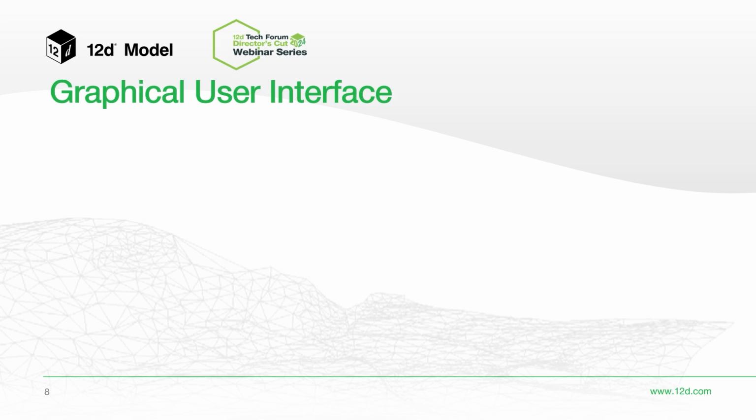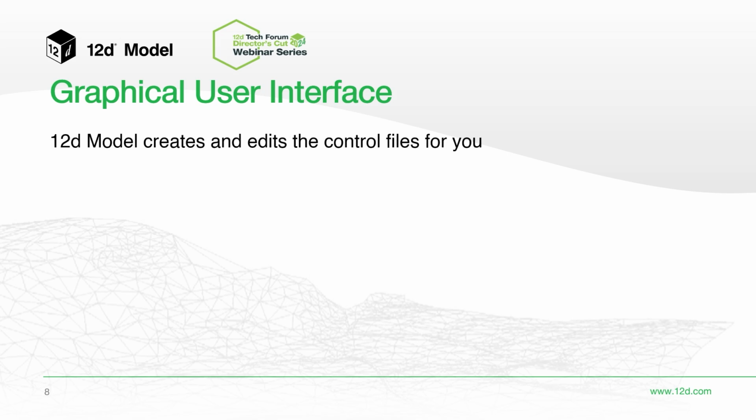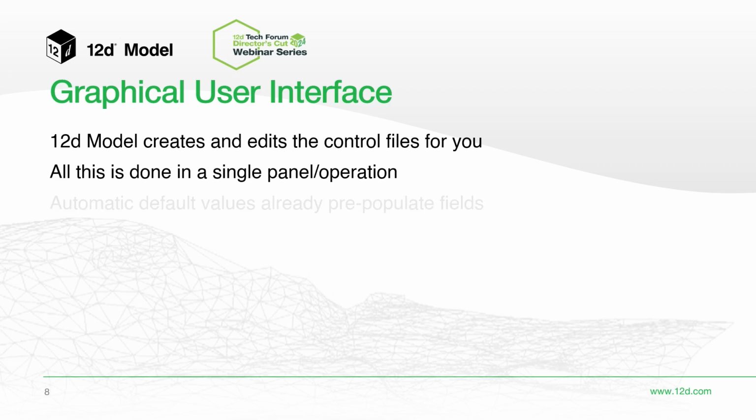Now the graphical user interface, there's been some major enhancements here. We create and edit the control files for you, just like the 2D quick analysis. But all of this is done as a single panel operation, so there's no quick startup with a quick analysis and then a TCF editor. We are building all of that in the background for you as you go. We have automatic default values already pre-populated in the fields, so if you want to change something you can, but you don't have to fill in a whole lot of fields before you can get a simulation underway.